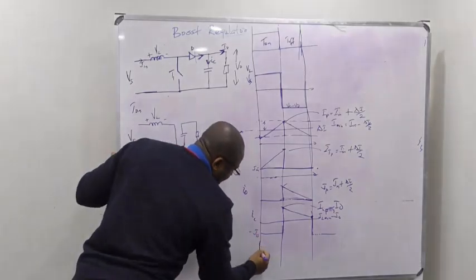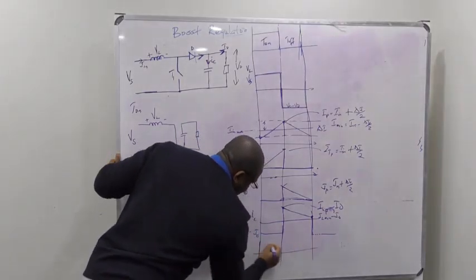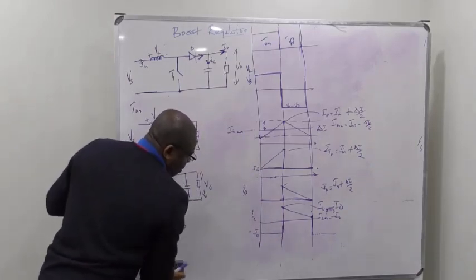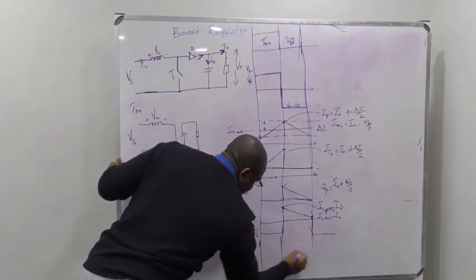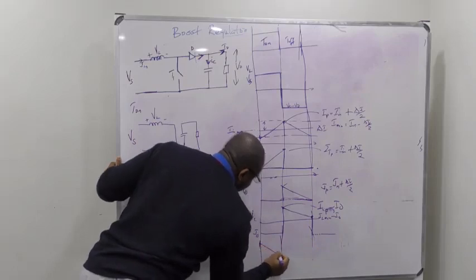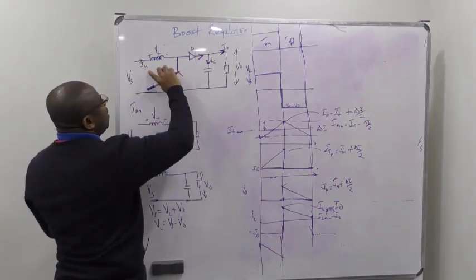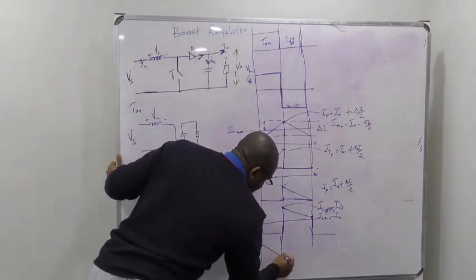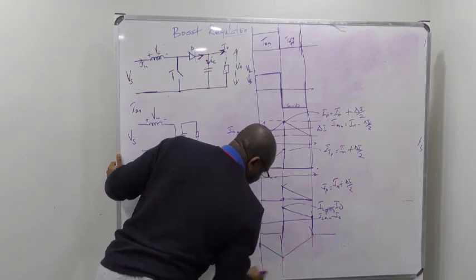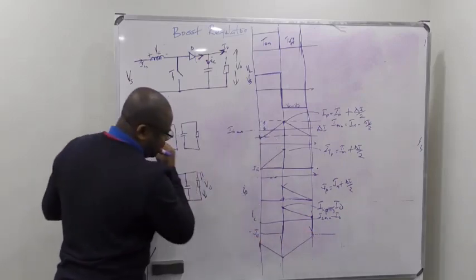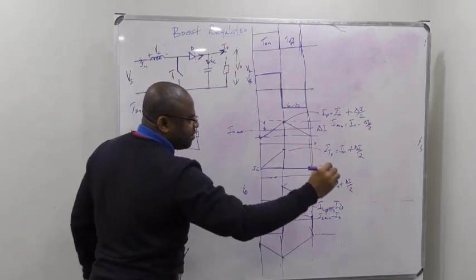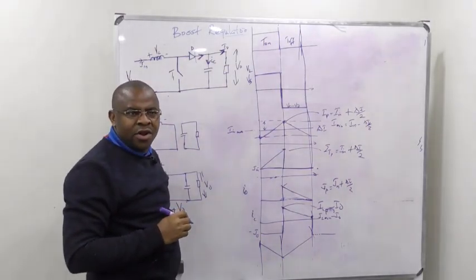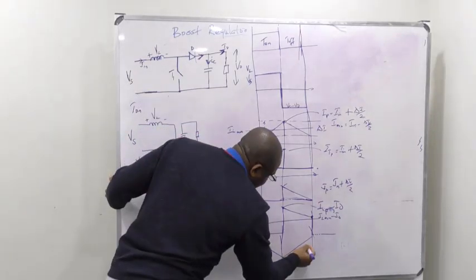So we are going to have a drop. You have dropping of the voltage. Immediately you turn this on, the current goes there again, and the voltage builds up. All right, like that. So this will be discharging, charging, discharging, charging, just like that. So you are going to have ripple there also at the voltage.